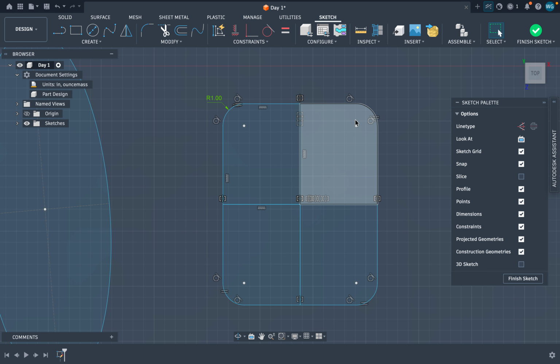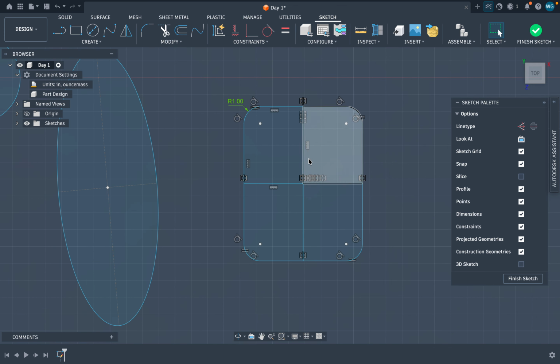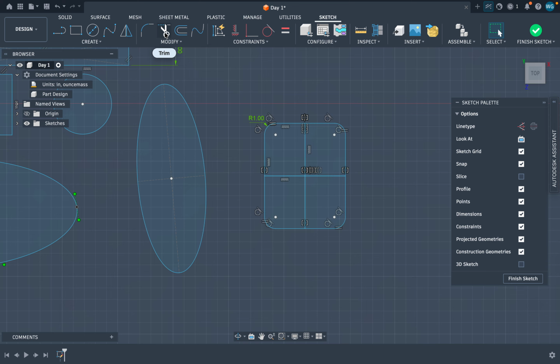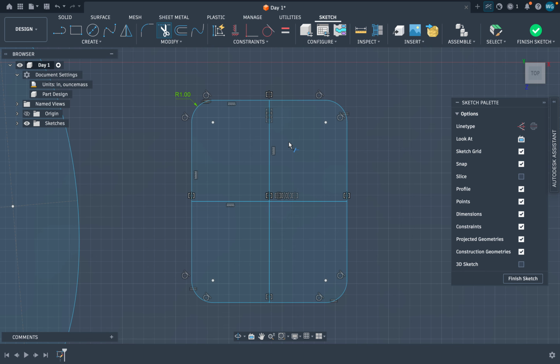Now we can see how every single one of the corners is curved at a 1 radius. The radius, from this dot to the line segment, is 1 inch. And then trim. Trim is the pieces that you cut off that you don't want. In this case, if we just want a rectangle with curved angles, we're going to trim the inside. We just drag it around, and now all the lines in the middle are gone.